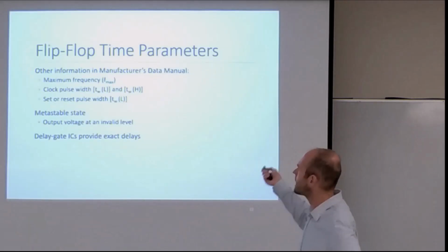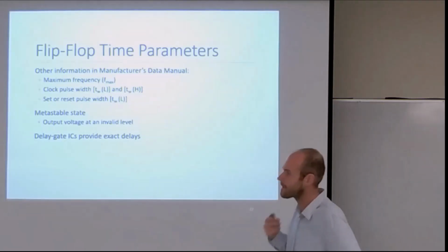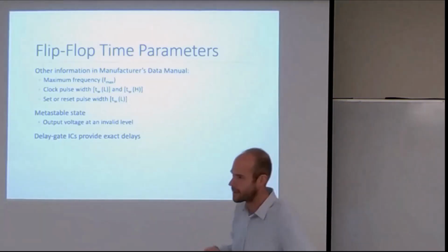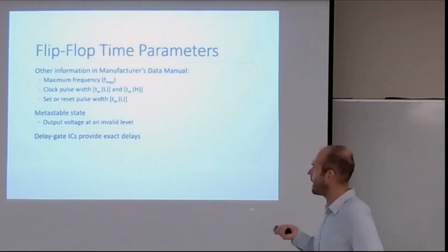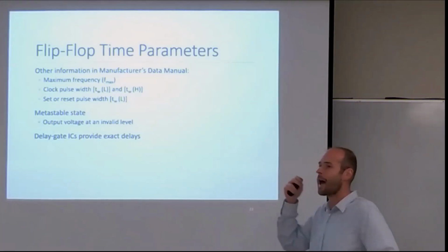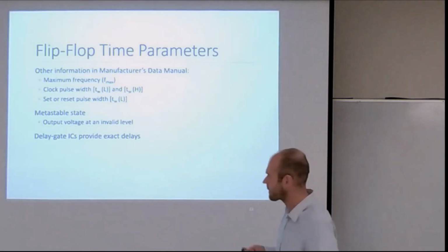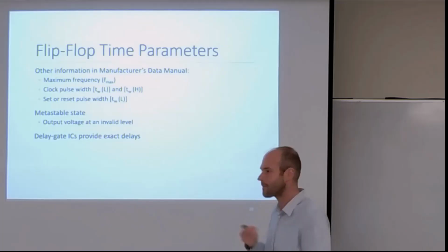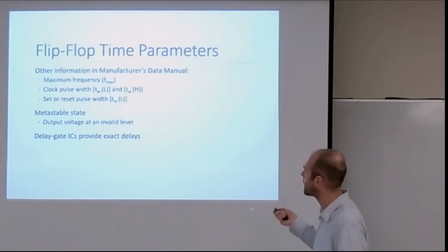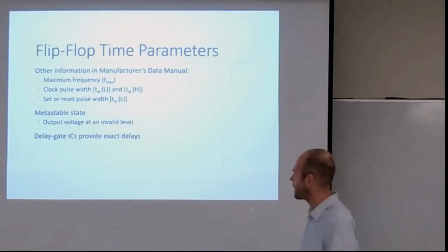So all of these items and more are in manufacturer data sheets. We've seen some snippets of those as part of the tests, and occasionally a tiny piece in the labs. But if you ever have a device that you are operating, maybe running with a microcontroller, for example, at high frequencies, you may need to reference some of these items to make sure you're working with it properly. And there are other items like maximum frequency that you can run a device.